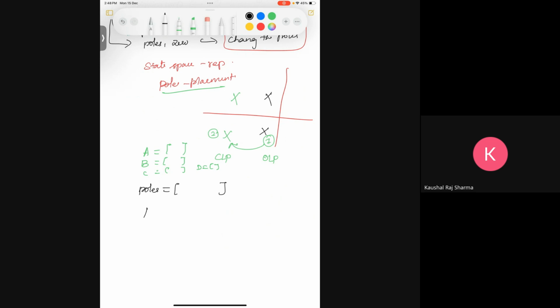Then you can find the gain K using the keyword acker(A, B, poles). This will find the proper gain value for the system so that your closed loop system poles lie in the defined location. This is what we do using the Ackermann method.